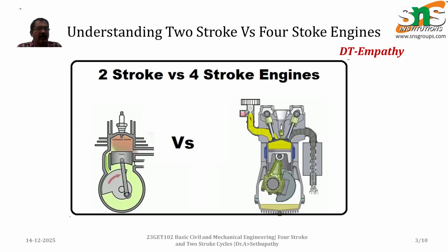Initially, the intake valve opens and the air-fuel mixture from the carburetor enters the combustion chamber due to the low pressure inside it. The high-pressure air-fuel mixture fills the combustion chamber. At that time, the inlet port is open and the outlet port is closed. The spark is ignited inside the combustion chamber before the inlet port is closed.